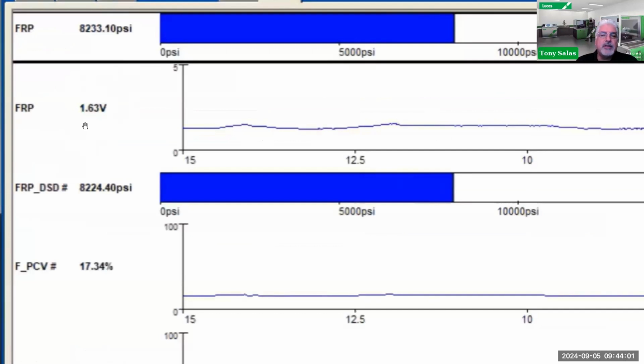And the way I know I'm in default is one of two ways. First of all, I will see that the fuel rail pressure signal reading, instead of reading 1.6, is going to be reading 0 or 5 volts all the time. If it reads 0 or 5 volts and never changes, you definitely got an open or a short to ground in that circuit going to the signal from the fuel rail pressure sensor. Okay. However, though, the other telltale is that the actual and desired are exactly the same. If they're exactly the same, that's definitely telling me I'm in a default value.